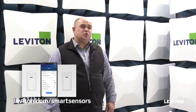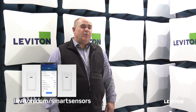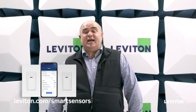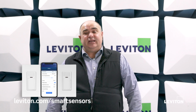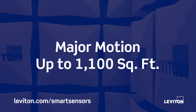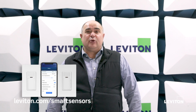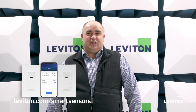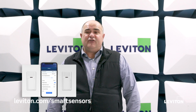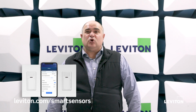the simple using switching. A couple more things to overview with regards to this smart Wallbox sensor is this latest passive infrared technology accurately detects minor motion up to 400 square feet and major motion up to 1100 square feet. And this is really important. I had said this is a great application for anything that's 400 to 500 square feet. And that's where I think it's going to really shine.